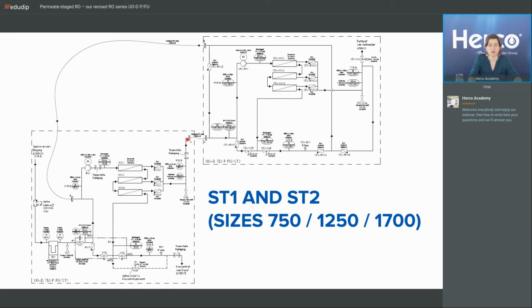And if you look closely, you also see you have one permeate recirculation, another permeate recirculation, right? That's stage 1. You have the permeate recirculation from stage 2, which I do not see immediately here. Yes, I guess that's that one. And you have a concentrate recirculation, if necessary, at the bottom of this block. So remember, all the flows that come back from the second stage, be it concentrate recirculation, be it permeate recirculation, they all go back to the first stage in just one hose.